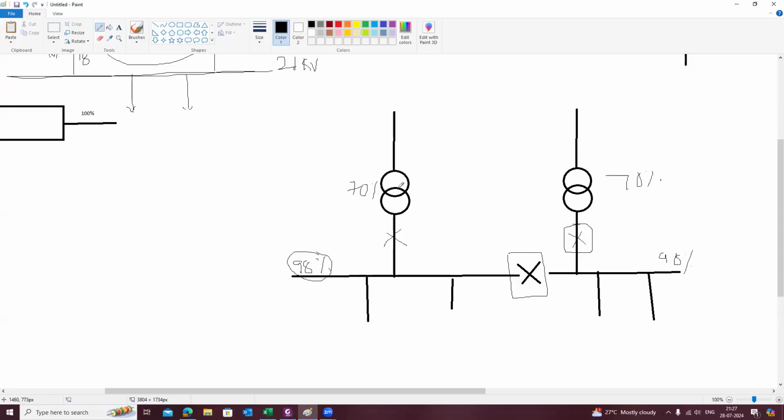So if you are operating at the normal tap at which it was operating, when you are feeding both the loads by this transformer, the voltage of the bus may come down to, let's suppose, 95%. And of course, the branch losses will increase and the equipment loading may reach 90%, something like that. So that means you have to evaluate the different configurations.